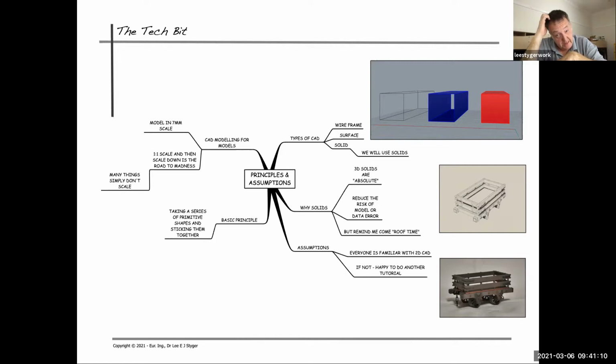It tends to be more foolproof in the way you go about modeling with it, but there are some little tricks to the trade, and one that I'll show you come roof time with the van, that I'll mention now, is the butt jointing of two solids. Although you can do that on the system, often when you output that for 3D printing or CNC machining, the conversion into those programs drops them back to their original native primitives. So you end up with a bigger bag of bits than you were necessarily expecting.